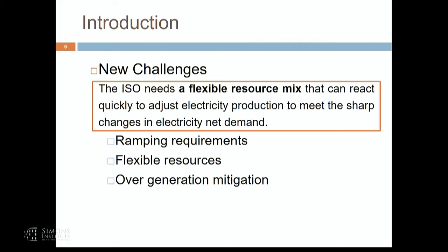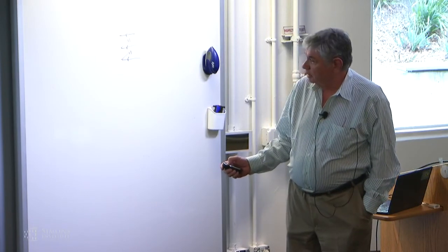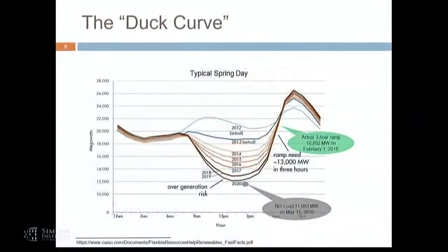Can you go back and explain the duck curve, because I've seen it so many times. The duck curve. I don't know what it means. So the duck curve, this is the original load profile. Now, during the day, you start to produce more and more solar. What the solar does is satisfy part of the demand.